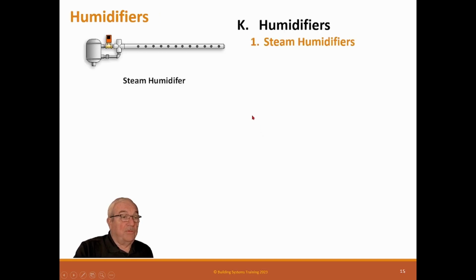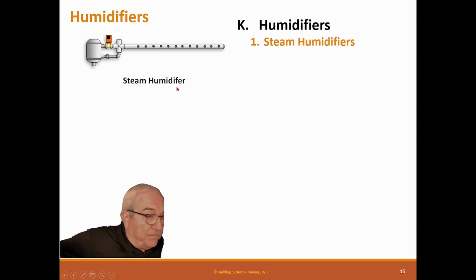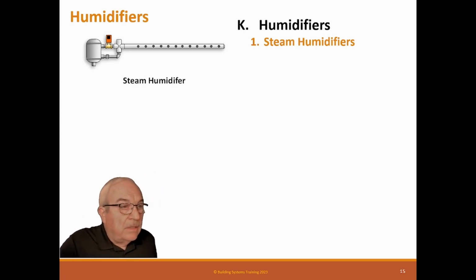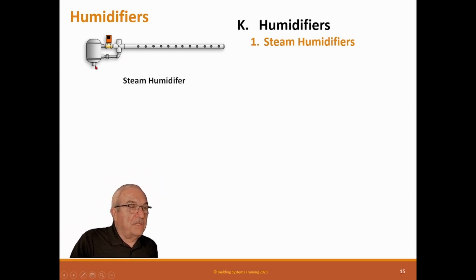Humidifiers, you get steam humidifiers, which are the gold standard, of course, which take live steam and distribute it throughout the ductwork. This is a module of ductwork. It has a valve that turns it on and off, modulating, so you can put a varying amount in there. The only problem with these is they need clean steam in the airstream. If you put regular steam that's been treated with amines and all these other chemicals into the airstream, you could cause indoor air quality issues. So we don't do that. Duct mounted, clean steam, like I said.